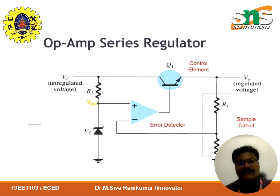We'll have a quick look at how an op-amp series voltage regulator works. It's a smart way to get a stable voltage. In this circuit, the op-amp compares the reference voltage from the Zener diode with a sample from the output. If there's any difference, it adjusts the transistor Q1, the control element, to correct the output voltage. This keeps the output steady even if the input or the load changes. So the op-amp acts like a brain, sensing, comparing and adjusting in real time.